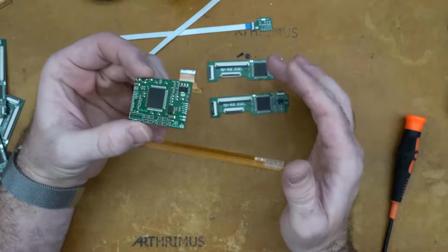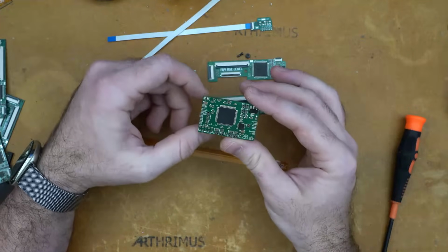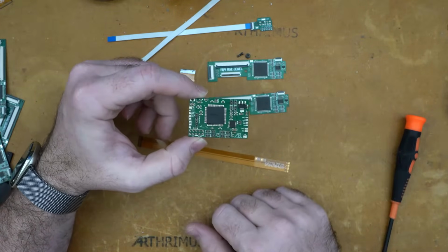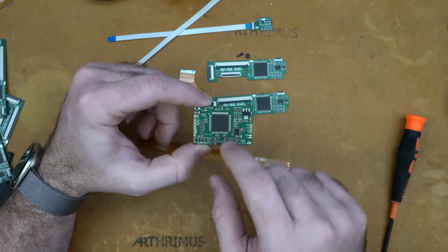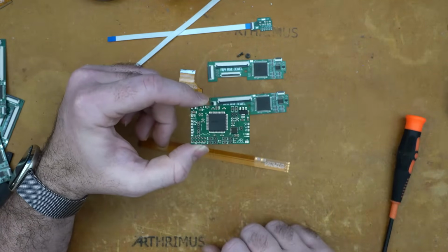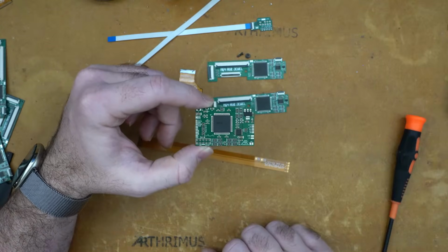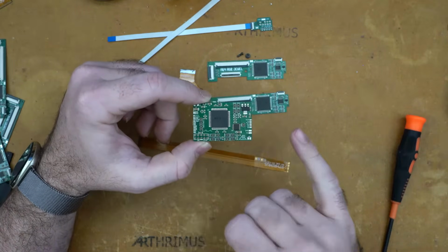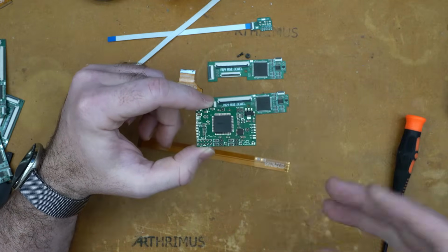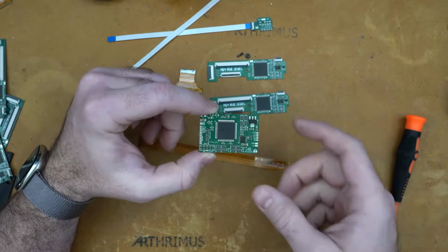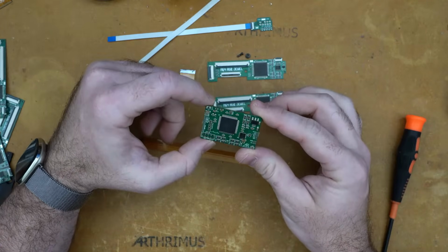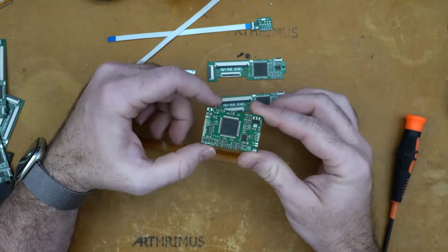This is my revised version of Bordy's design, but basically it's the same concept. It uses the CPLD to convert the digital signals into analog signals using this resistor ladder DAC. It's just a more compact version of Tim's design, and it was open source, so anybody could make them.